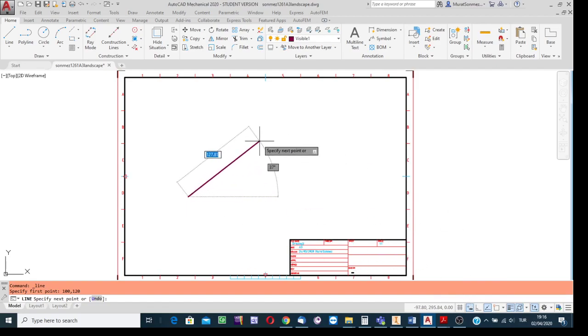See the simulated arc, in which direction is it extending relative to the horizontal dotted line? Then write the inclination angle as measured in the direction in which the arc extends from the horizontal reference line toward the line which is to be created.